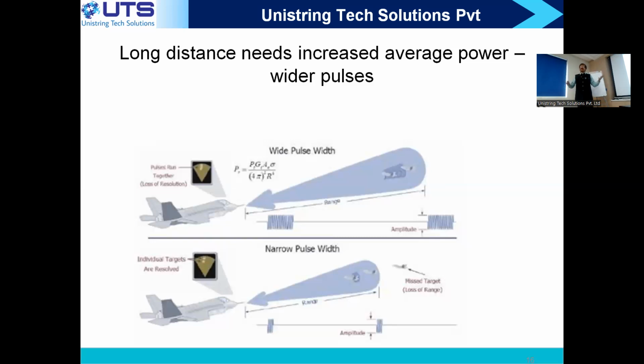So probably there can be a very detailed workshop on pulse compression techniques for postgraduate students who are already into radar signal processing. So pulse compression is a method where you still do it like this, but improve your range resolution. Your pulse is still broader for your average power detectability chances, but you compress the pulse. On the air, the pulse is still 10 microseconds, but in your processing, you get an advantage.